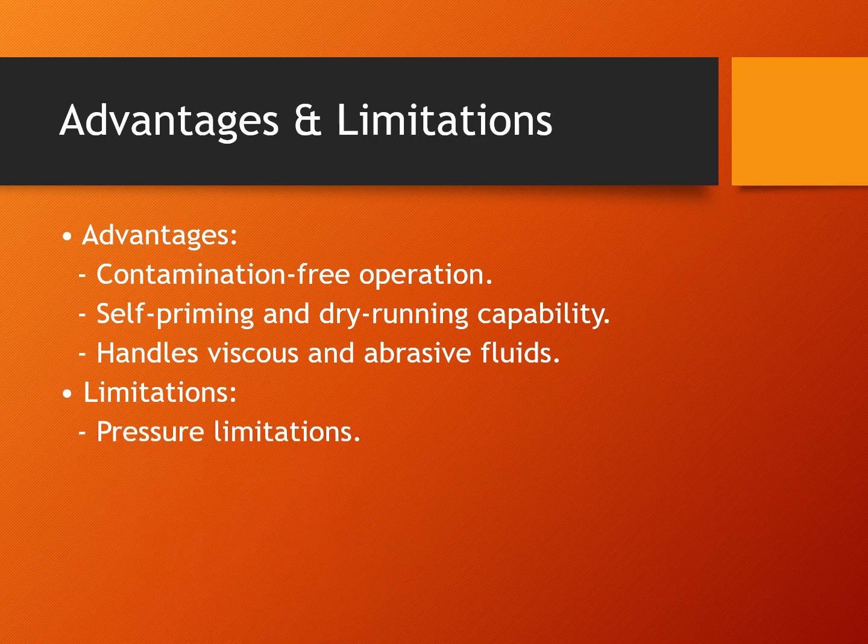So it has some limitations. Also, it has pulsating flow, more like turbulent flow. It's not smooth. The flow in the tubes is not smooth. And then there's also tubing wear over time due to friction between the tubing and the rollers.